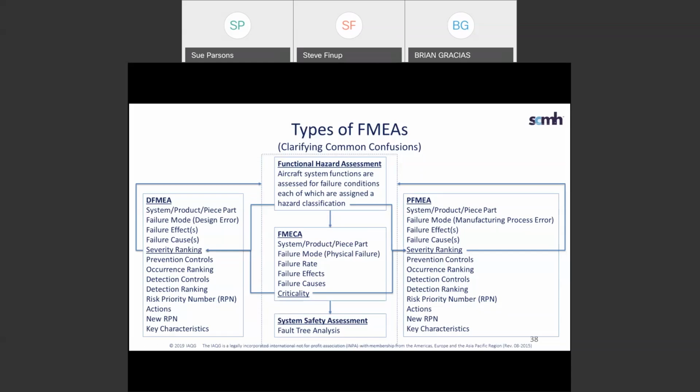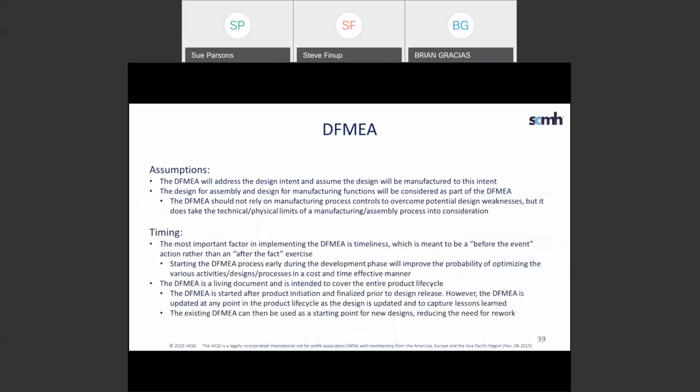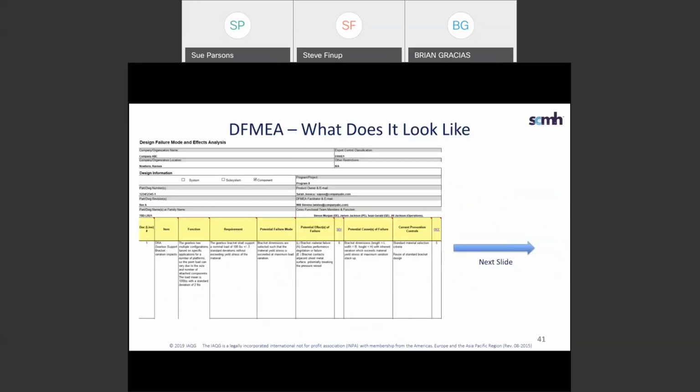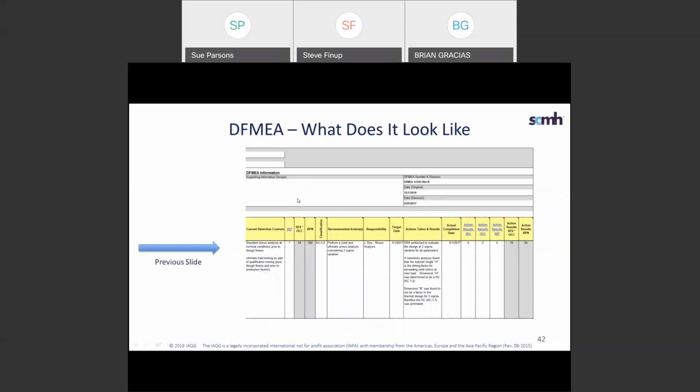Is there any guidance in APQP for how to rate the three values that are multiplied into an RPN? Are there scales for each one somewhere? Yeah, so for each one, you will have a ranking table. For severity, we're defining a ranking table that goes from 1 to 10, same for occurrence and same for detection. So that'll be part of the template that we'll be producing.